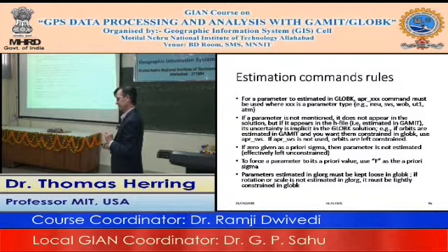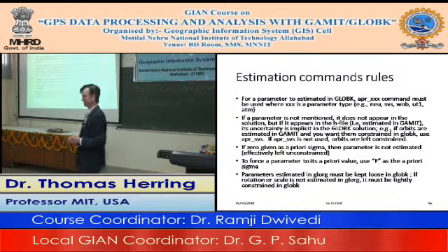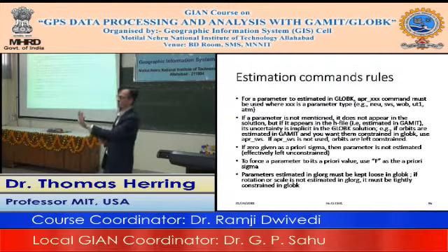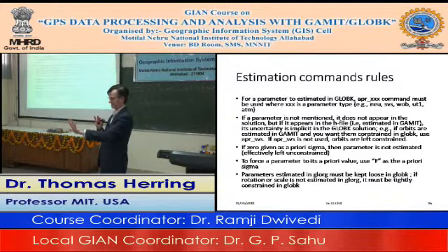Does it add some random noise? No, it's literally 0. Kalman filters work in covariance matrix space. There is no weight matrix. So we don't make any inverse of the covariance matrix? Nope, you never invert.